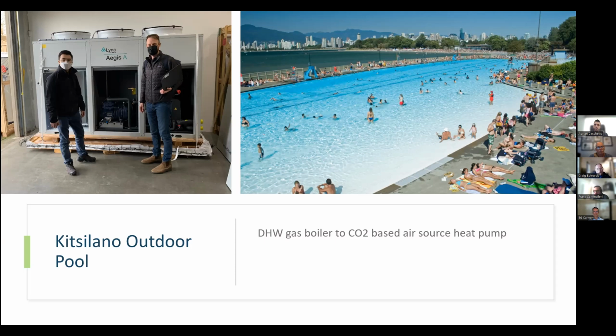So you design it with a reverse cascading system, where the heat pump sends the hot water in reverse flow through the 3 tanks, in reverse to how the cold water comes into the system. And then we put in a controls package. We hooked it up to our building automation system, our DDC system, so that it's completely controlled. It turns on when the storage tanks get fairly cool, and then it gets charged up. The storage tanks get charged up like a battery, and then we turn off the heat pump when it's charged up enough that we start getting too warm a return water temperature going back to the heat pump.